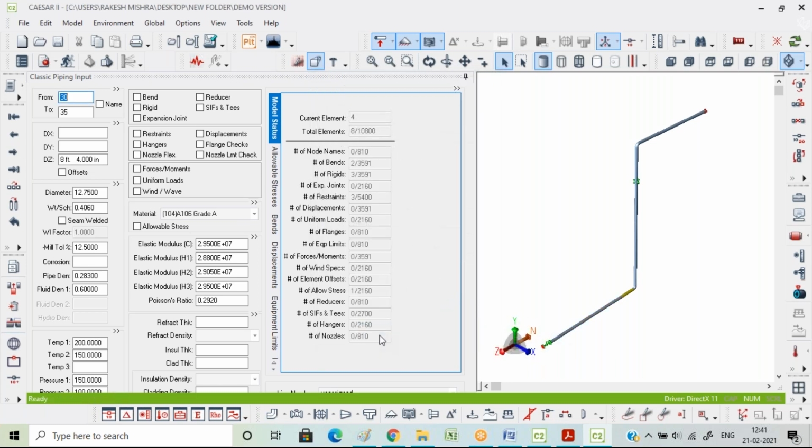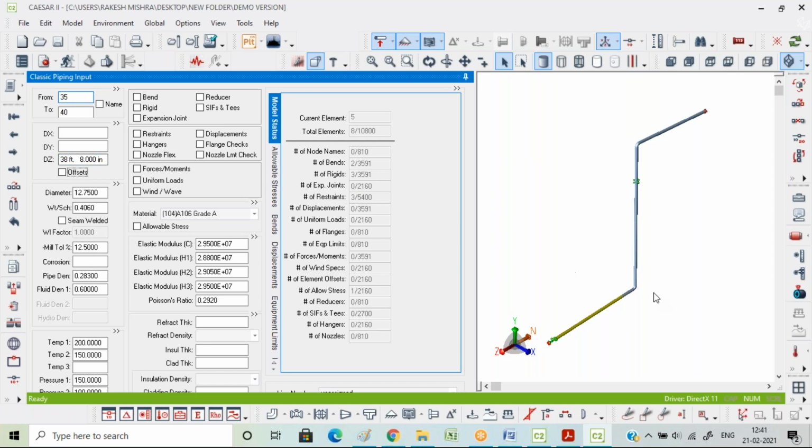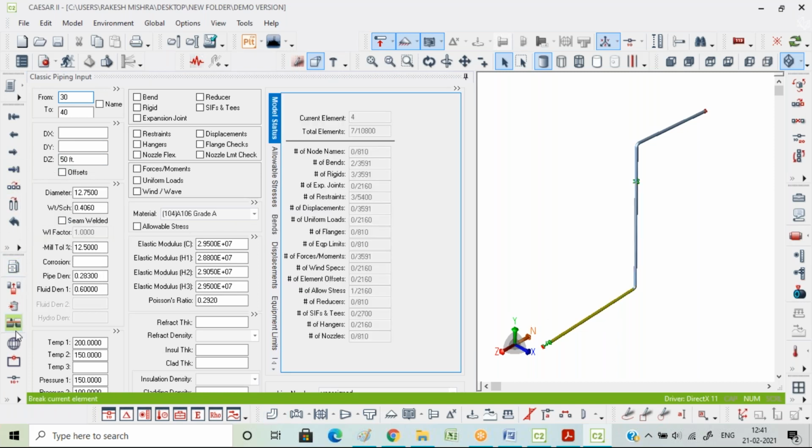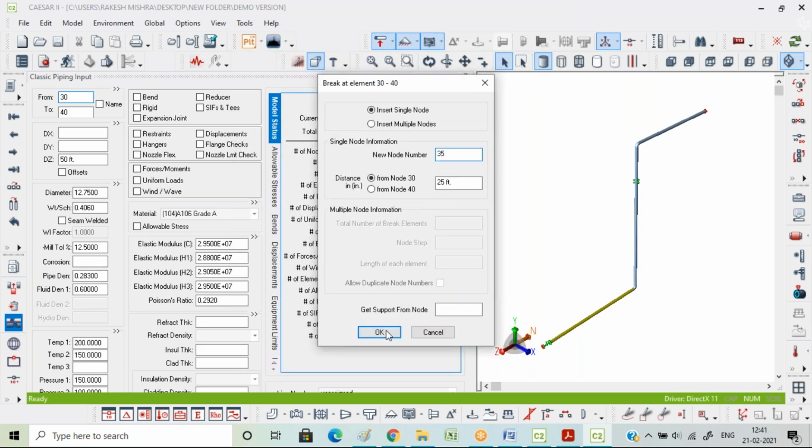Yeah, it's fairly near this. We'll still increase it by somewhat, because let's not place it near this thing, because there's always an axial stop over here. This axial stop will always create a problem. It will start acting like you're installing 2 axial stops in the same line, which is very much wrong. Okay, so it's better we install it somewhere in between. Let's see.